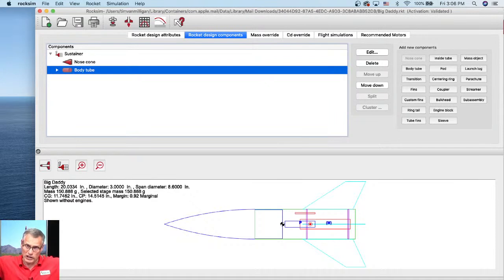They have a really long Kevlar and a short elastic. They're in parallel, so they're two lines that run parallel to each other. As they come out, the elastic is stretching and slowing the nose cone down. But if it gets too far and the elastic breaks, then the Kevlar will still keep everything together. And so you get the best of both worlds: the slowing effect of elastic with the strength and durability of Kevlar.